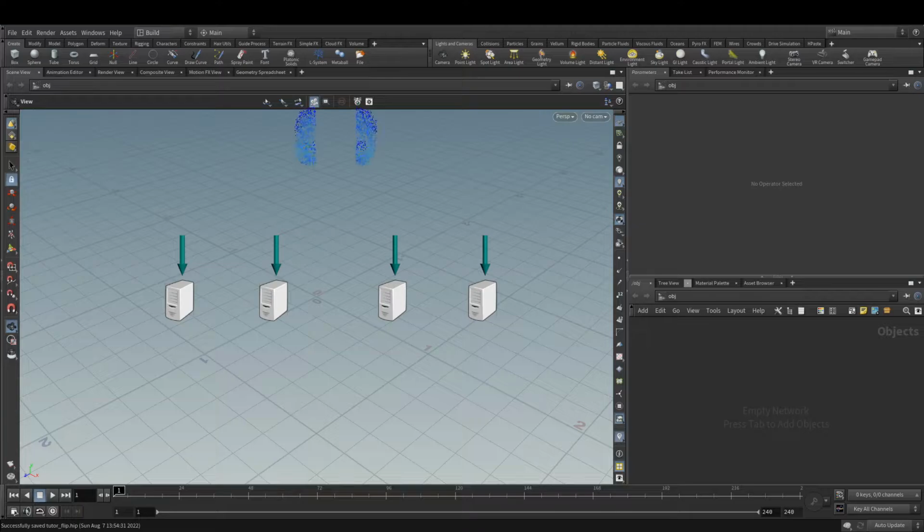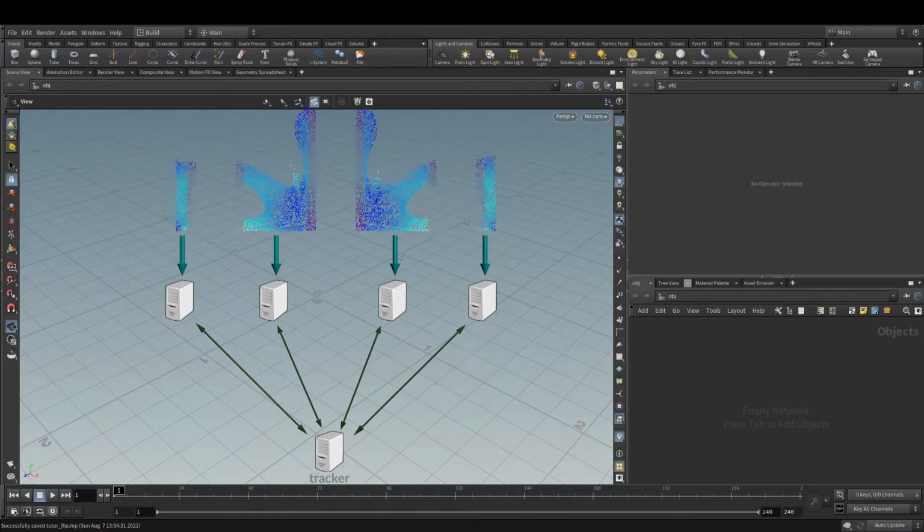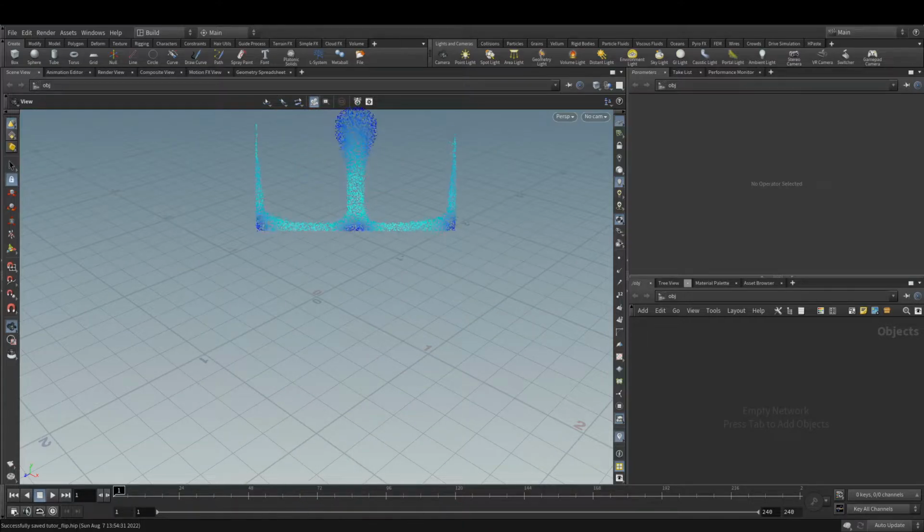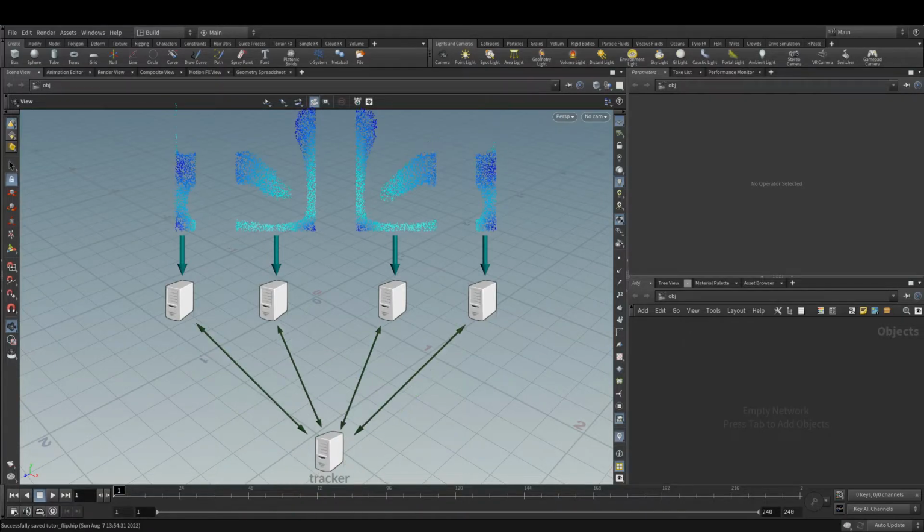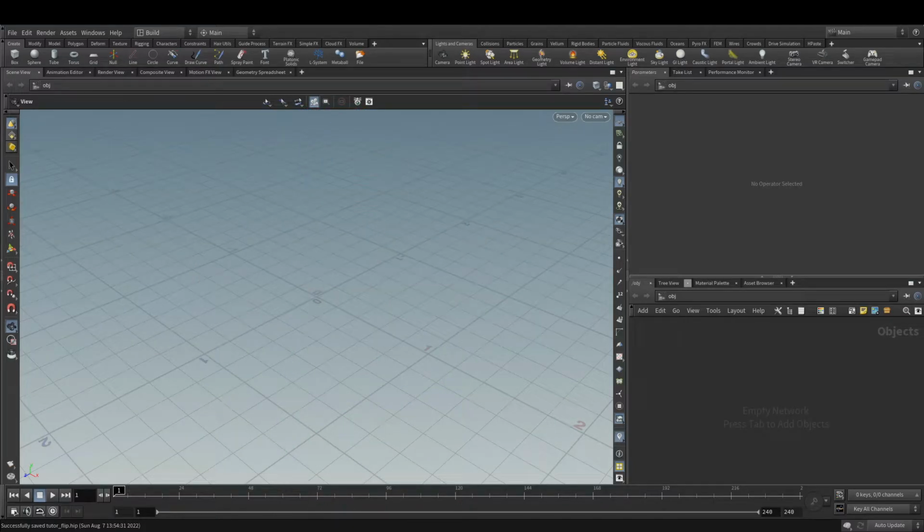The way it's done in Houdini is with a special dedicated lightweight server called a tracker. So a tracker needs to be running, and all slices need to know its address in order for the distributed simulation to run. Obviously, there is no point distributing a simulation in a way where all slices run on the same computer. It's way better to just compute the whole simulation without distributing it. Slicing is not efficient and may produce undersolved artifacts on slice borders. It is somewhat of a last resort that you do only when you really have to.